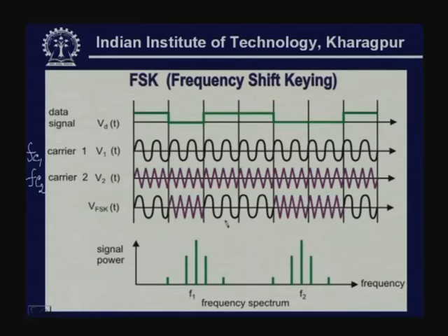Here you have got two 1s, so we are sending Fc1, then two 0s, so two Fc2s, and then Fc1. So, here we can see that the frequency shift keyed signal looks like this. That means, here is your frequency shift keying signal as we receive it at the receiving end. So, we have two different frequencies Fc1 and Fc2, and they are sent alternately depending on whether the data is 1 or 0.